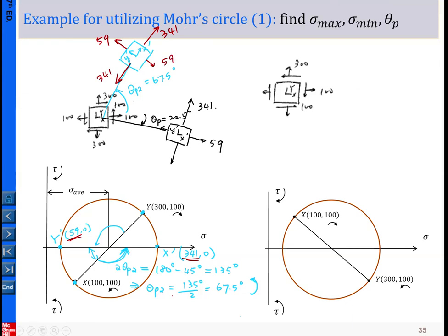Okay, so here you have two options to present your calculations for principal stresses and principal directions. Here we have two values of the principal directions: this one counterclockwise, and this one clockwise. And it doesn't matter which option you go with, you can see the distribution of the principal